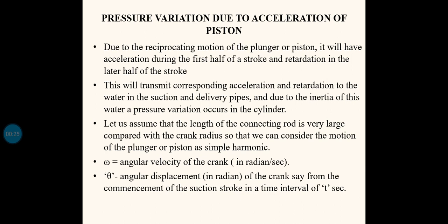While the piston is moving from left to right, that is during the suction stroke, initially the piston will be having an accelerative motion, but at the end of the stroke the piston has to stop, so the piston will be having a decelerative motion. Same thing will be there in the case of the delivery stroke also. Initially the piston will be having an accelerative motion, whereas at the end of the stroke the piston has to stop, so the piston will be having a decelerative motion.